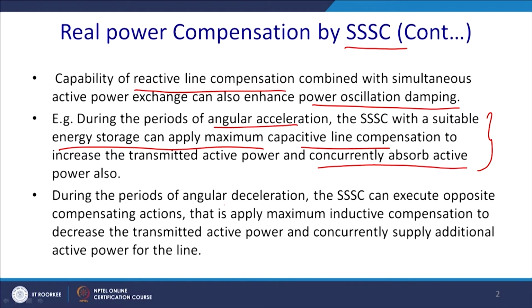During the period of deceleration, when energy comes down, SSSC can execute the opposite compensating action, that is, apply the maximum inductive compensation to the line to decrease the transmitted active power and concurrently supply the additional active power to the line.